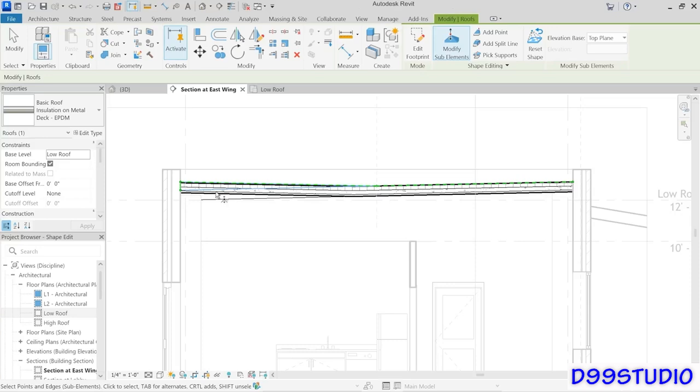Now, if you look carefully, you can see that we've still got this blue line here. So the slope is continuing down to those drain points off in the distance, kind of through the thickness of the roof there. We could stop here. This would be a valid roof. Sometimes folks do taper the actual structure of the roof. But if instead you want a flat underside of the roof and you just simply want to build up the roof with tapered rigid insulation, then there's one additional step.